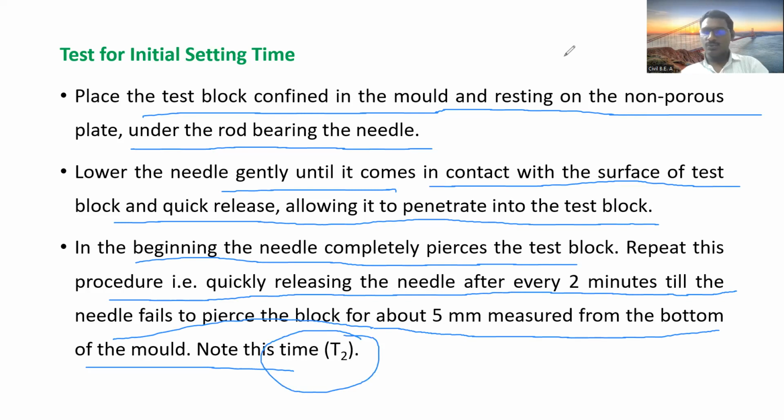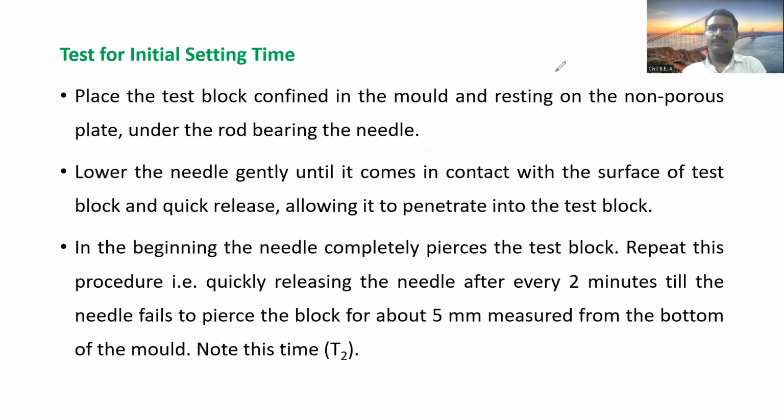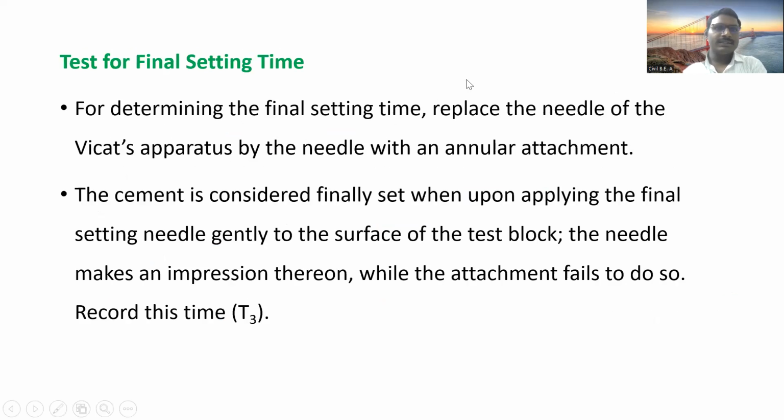Then what we have to do? Then determine the final setting time. So if the needle reaches 5 mm from the bottom, that is the initial setting time. Now we have to go for the final setting time.